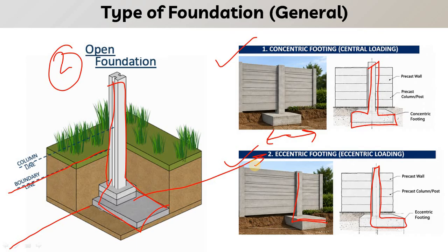In that case, when a boundary wall has to be made in a common plot, we can split the foundation on both sides. There we don't have any limit for the boundary. When it is an external wall, definitely we need to consider the plot limit, or construction line, beyond which we cannot extend our elements or construct anything. So in that case we consider eccentric footing.